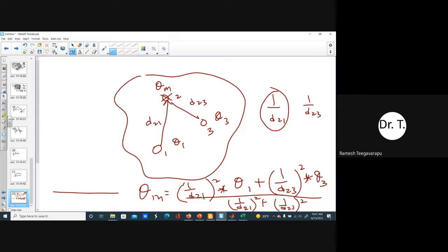The interesting thing is that this is the most commonly used interpolation method for many hydrological variables, especially temperature and precipitation. Now, daily precipitation, yes, but sometimes daily precipitation may not work very well using this kind of distance-based interpolation. Or it also depends on the climatic region. In some climatic regions, precipitation varies based on distance. So in that case, distance can be a surrogate for association. So you can estimate the missing values by the inverse distance weighing method. It's called IDW. Okay, so that is most commonly used even for gridded data generation also.